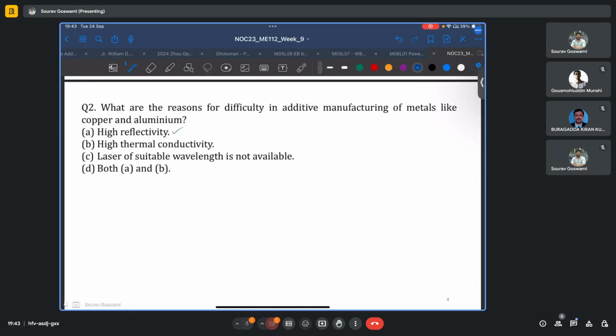What happens is when the substrate or the pre-built layer is bombarded with the energy beam, often rather than the localized rise of temperature, which may lead to melting, because of the high thermal conductivity, the energy is dissipated quicker than it is getting received. So while the bulk temperature of the material gets raised, there is no localized melting because in a local region, the heat is getting dissipated too quickly and there is simply not enough energy buildup for any melting to happen.